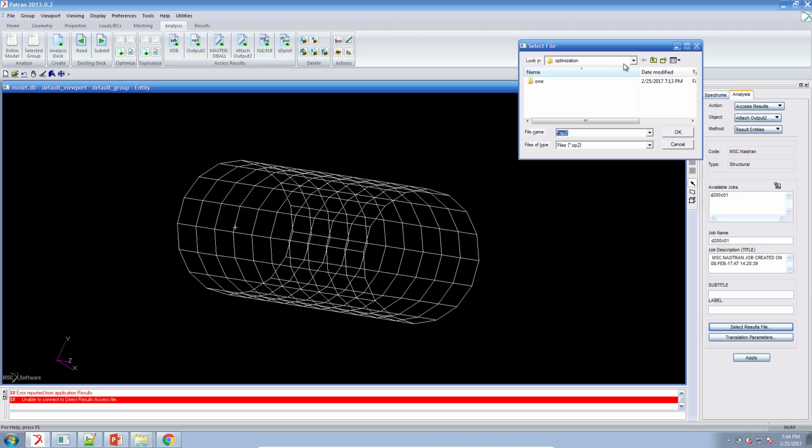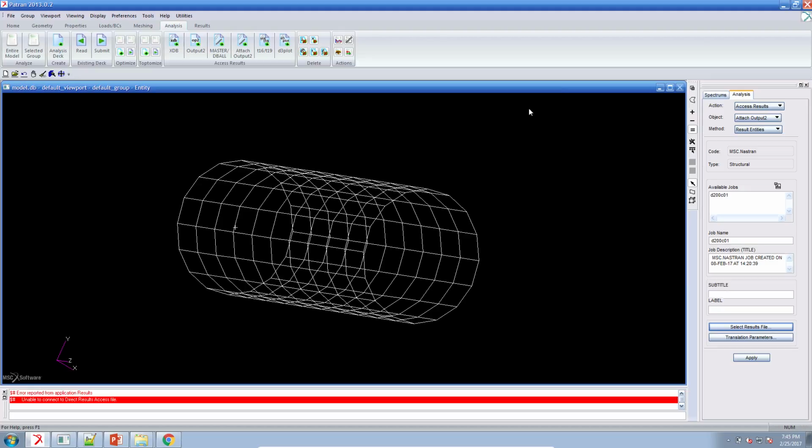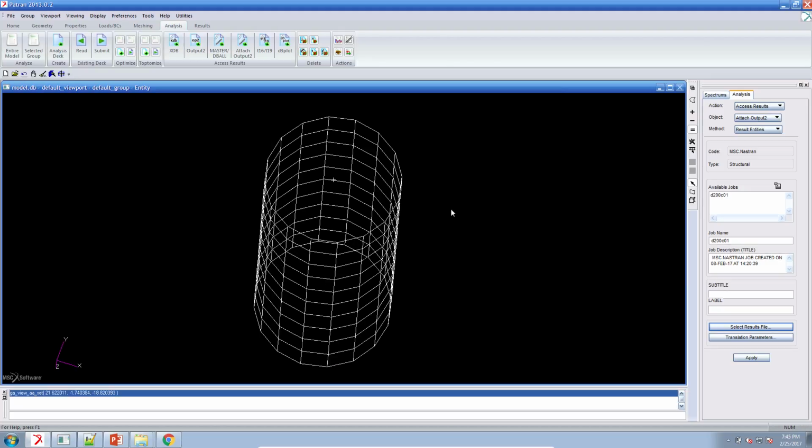the tube is constrained in a way where the tube can expand radially without restriction. The benefit of this is that when we look at the stress results or the failure indices, you find that they are uniform and consistent for each element. So instead of applying this design constraint to each element in the entire model, we can actually just restrict one element, and we have the confidence that since all the results are the same for the other elements, just constraining that one element will be sufficient for this.